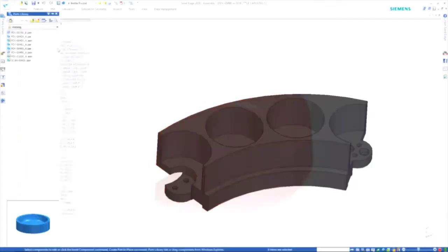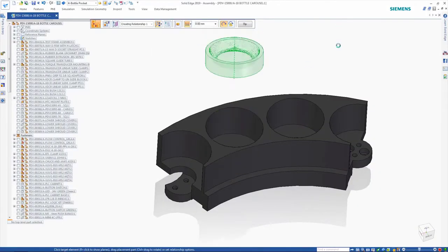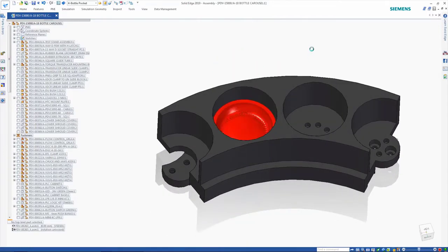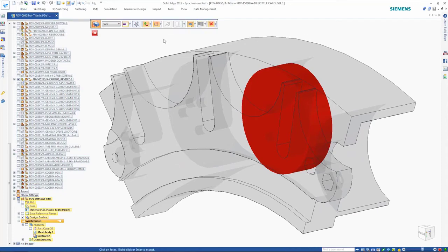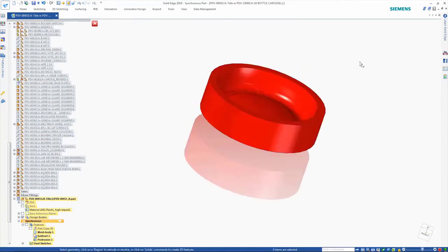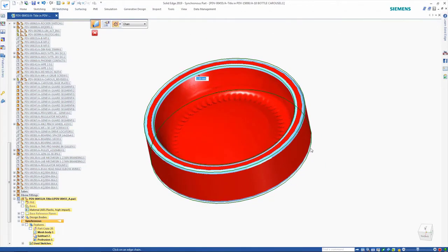Now that the part is done, it can be added to the assembly. Once again, even though this is a mesh body, regular assembly relationships can be used to ensure correct positioning just like they can on a regular solid model. Additional geometry can quickly be added to this mesh model for location purposes. Once again, convergent modeling makes this possible. This even allows rounding to be applied to the sharp edges of the mesh model.